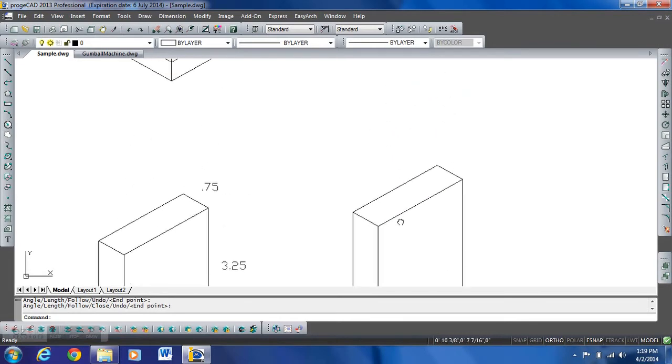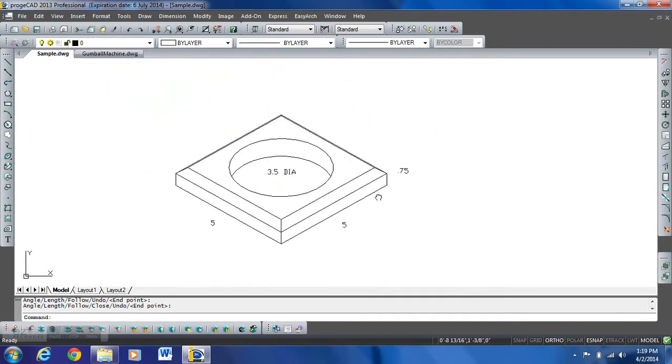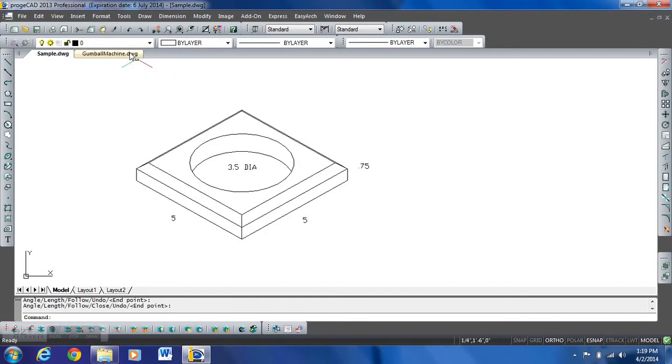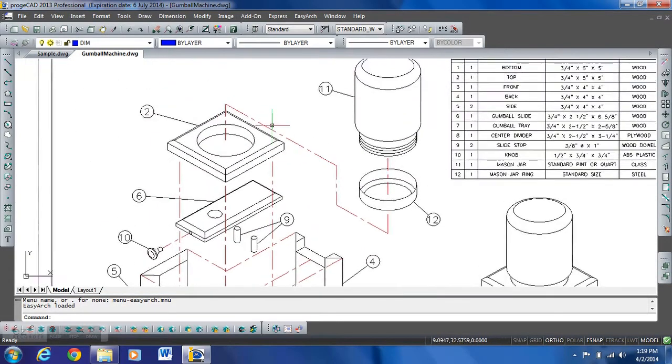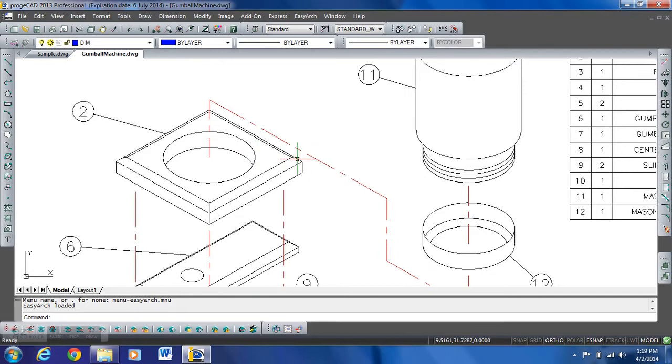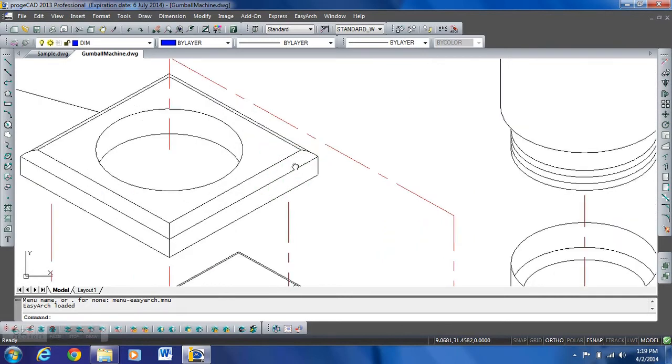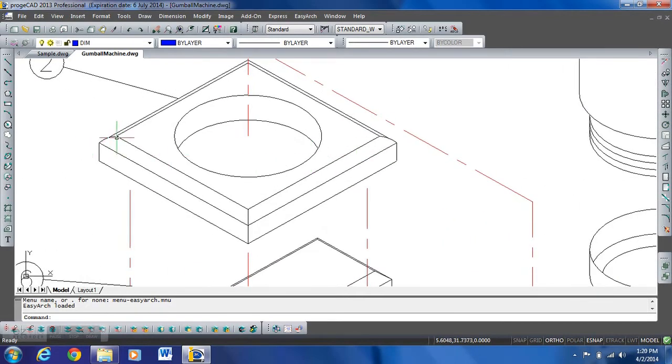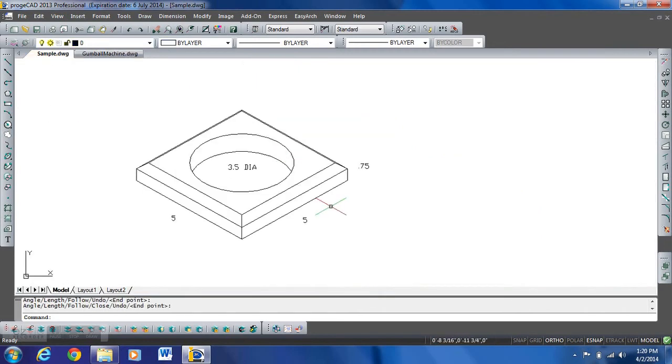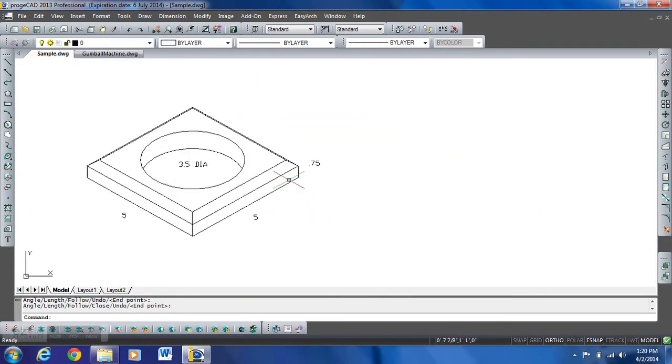Next thing we're going to work on is the top. And when you look at the completed drawing, you'll see that the top view should be filleted on the top and the bottom. They're a little more difficult to show. I think we're going to make life easy for us just by giving ourselves like a chamfered look just to at least represent it. So on our sample drawing, these are the proportions we need to work with. So let's start on the top isoplane, and we're going to start by drawing in our top view.